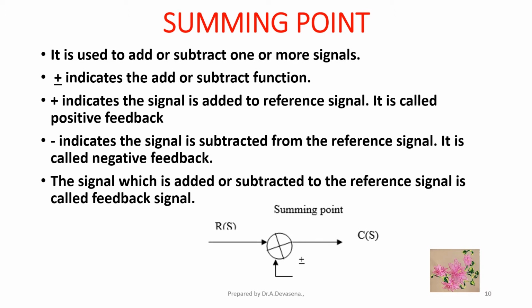This is a representation of a summing point. Here we have a summer. To this, one input is the reference input R of S and the other input is the feedback signal, and plus or minus indicates whether positive feedback or negative feedback is applied to the summing point.